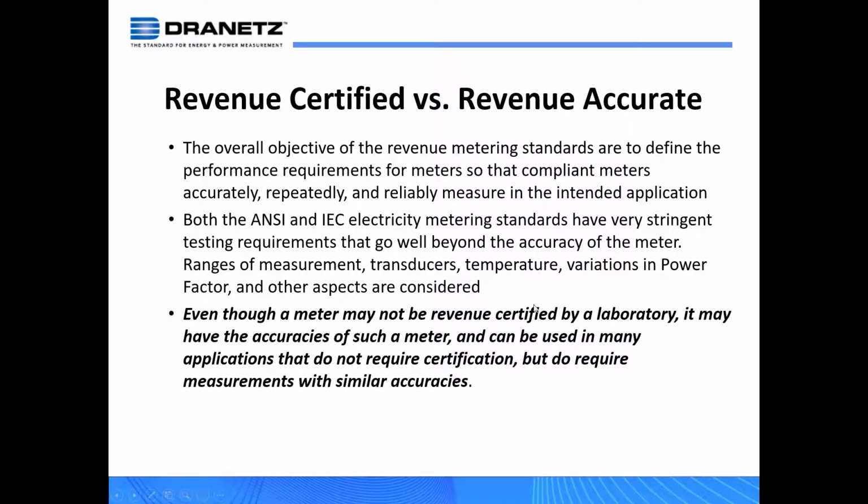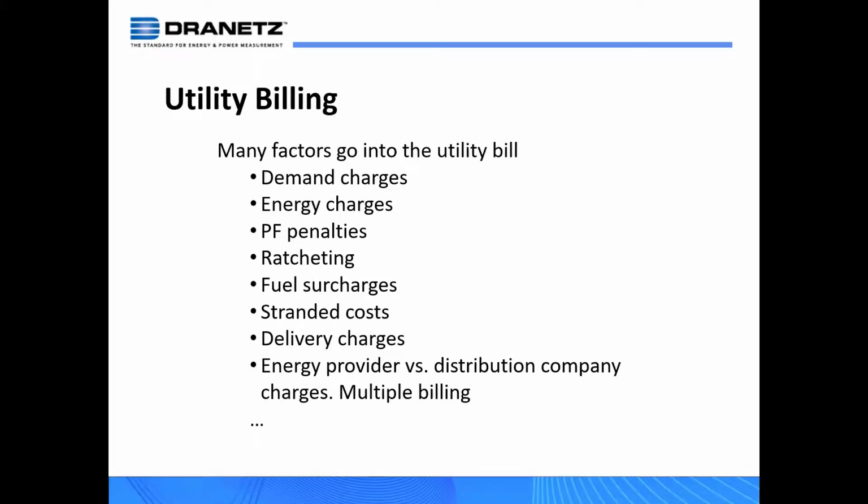And those may be in check metering to verify that a utility meter is operating correctly. In fact, there are certain areas, I know the city of New York requires that a certain percentage of the meters are random sampled to make sure that they are operating correctly, okay? Or from your own perspective, if you want to just put something in parallel with your utility meter to make sure that you're being billed properly. So, these are different applications, and of course, those within your facilities to monitor your own energy.